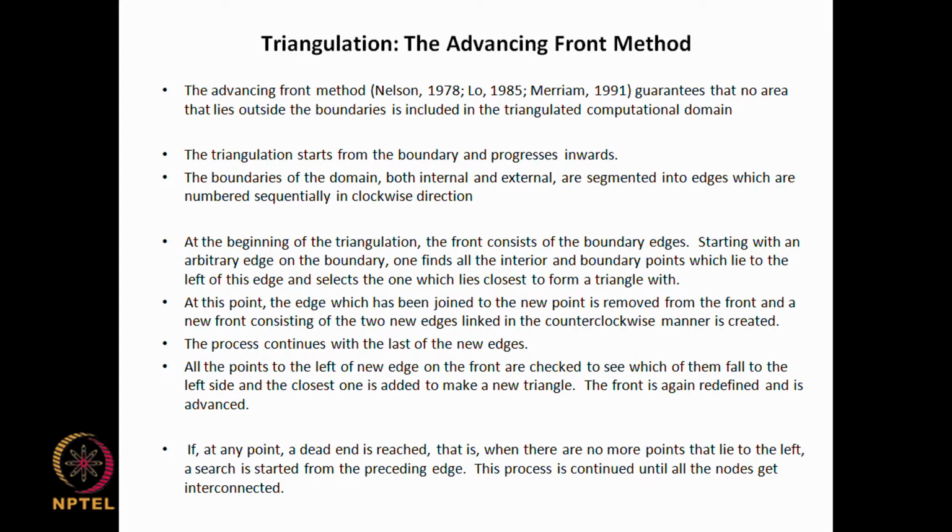We have seen the nodalization in the last lecture, and in this lecture we look at one method for triangulation. We mentioned that triangulation is not a trivial thing. This method, the advancing front method, was developed in the late 70s. It has one attractive feature: it guarantees that no new area that lies outside the boundaries is included in the triangulated computational domain. So, this has that guarantee.